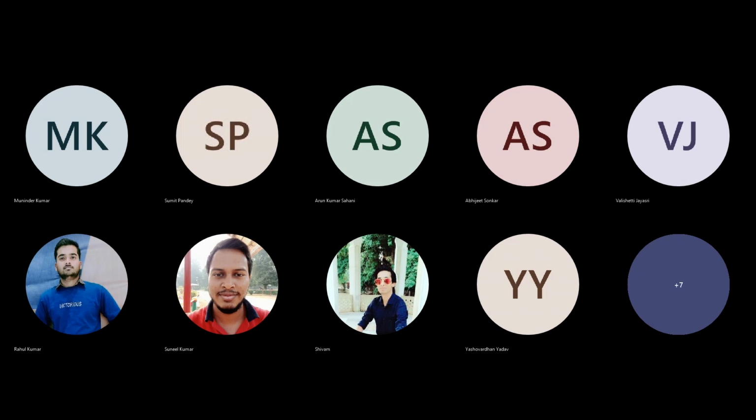The equally spaced segments along the voltage line from V minimum to V max, they are n. We select n is equal to 256. So to represent them, 8 bits are required. If you further increase this number beyond 256, then we require 9 bits.